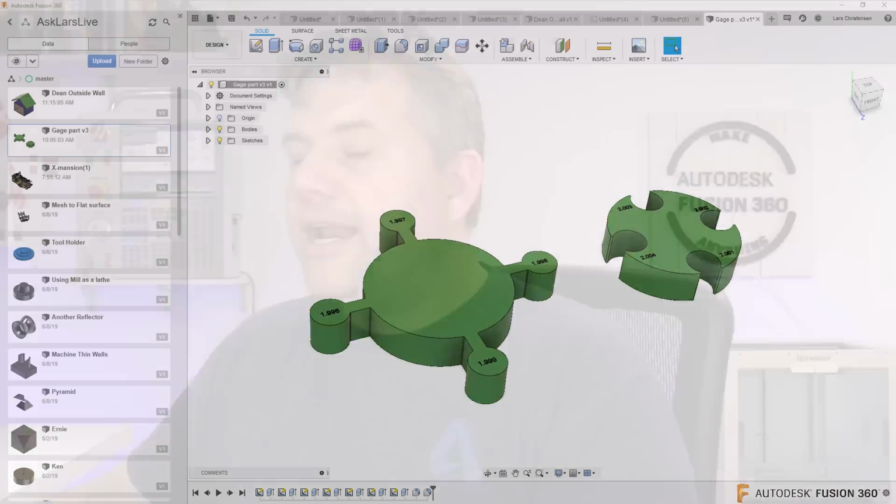The other thing, and I hope this is useful. So again, that file, download it. The other thing, Bernie, you're talking about is that if you are using the hole thread tool inside of Fusion, just like we did the counterbore a little bit earlier in a video, if you're using the thread tool, it actually makes the hole smaller or changes the size when you apply a thread.